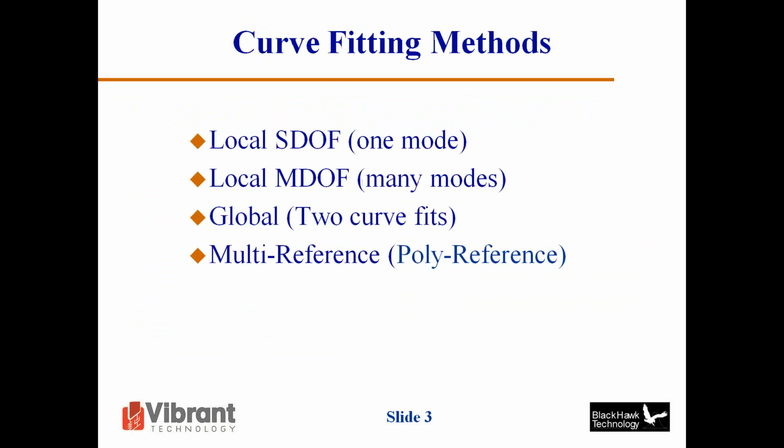These are different curve fitting methods that we have available in ME-Scope. They kind of go from the simple to the more complex. In previous webinars, we covered the first three methods. When we talk about local SDF, what we mean there is one mode at a time, single degree of freedom. So the curve fitter is working on one mode at a time.